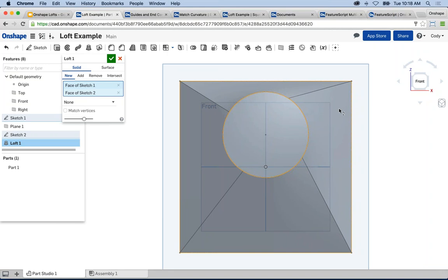They just click 2 faces, and ooh, that looks ugly. I'll find something else. It's easy. It's an easy problem to correct. So I do want to point this out. But by default, again, you can loft between the contours, but you may not get the exact twist that you're trying to. So let me show you an example of what I might do in this situation.